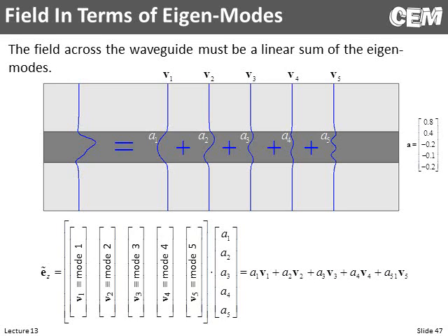So let's interpret this a little bit. It turns out that your field can look like more than what is in those modes. So here are your Eigen-Modes, and let's say the field in the actual cross-section looks crazy. This doesn't look like any of these modes. However, whatever the field looks like has to be some kind of combination of all the Eigen-Modes. I'm only showing the guided modes here, but in fact it's all the other ones too. There has to be some combination of those with these complex weights that would all add up to give you whatever the field is here.